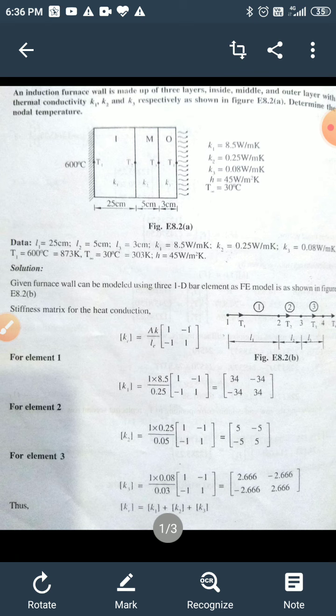First of all, we come to know what conduction is. Conduction is the transfer of heat through materials without any net motion of mass of the material. This is represented by the equation Q is equal to minus KA into dT by dx. Q is the heat transfer rate in x direction in watt. K is the thermal conductivity in watt per meter Kelvin, a property of the material. Already we discussed in the first chapter, when we found the displacements or the stiffness of the stepped bar, E is the property of the material, that is Young's modulus. But in case of heat transfer, K is the property of the material, in watt per meter Kelvin, and dT over dx is the temperature gradient in Kelvin per meter or degree centigrade per meter or centimeter.